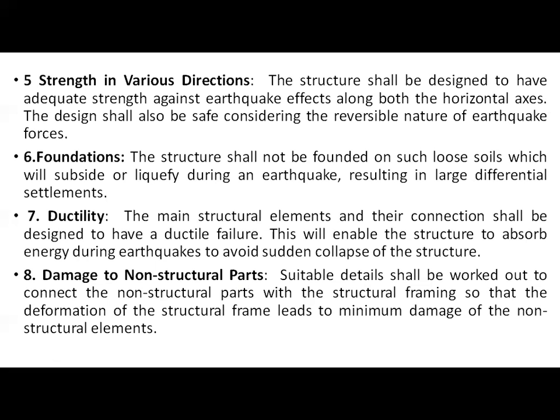Because of the collapsing, because of the minor damages of that non-structural element. Okay, the suitable details shall be worked out to connect the non-structural parts with the structural framing so that the deformation of the structural frame leads to minimum damage of the non-structural element.